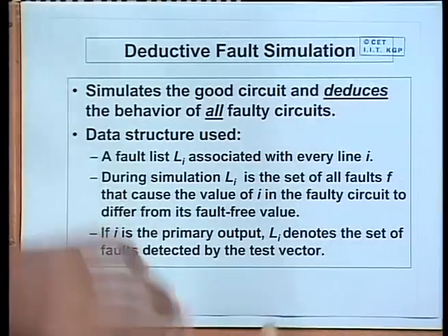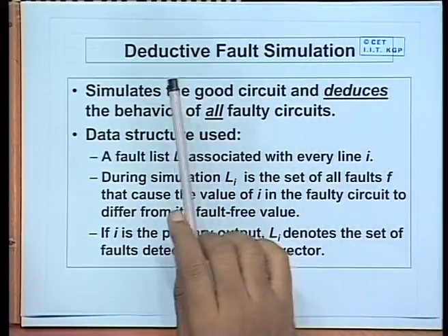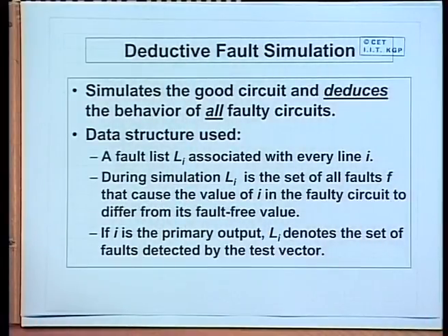Let us look at some other fault simulation techniques like deductive fault simulation. Now, deductive fault simulation is an interesting method. This is an event driven fault simulation in the sense that you only simulate a gate if some event occurs in one of the inputs. If there is no event occurring, then there is no need to simulate that gate.